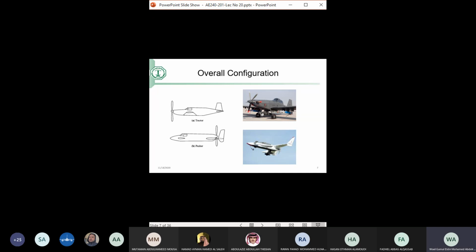If this happens, the aircraft will be unstable. But if the CG is forward of this neutral point, the aircraft is safe and stable. The more forward, the more stable the aircraft is going to be. So from a stability point of view, a forward engine is better than an aft engine because it brings the CG forward. So that's definitely a consideration.